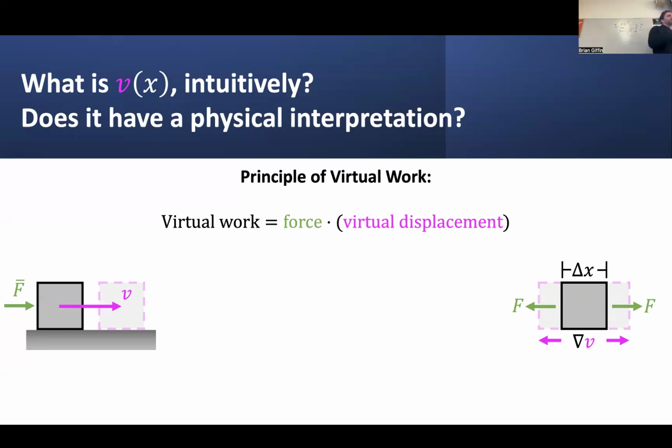Now, the principle of virtual work established a relationship between the external virtual work done on this system, let's say any external forces applied to this block to move it some finite distance. It established a balance between external virtual work done on the system and internal virtual work done in, let's say, stretching the material locally. And that could be measured by considering how much some block of material stretches if it were subjected to some virtual strain field.